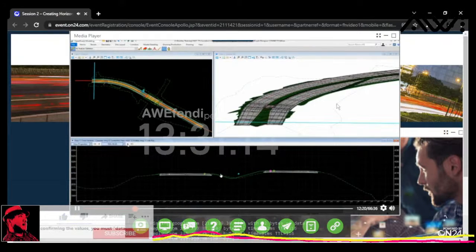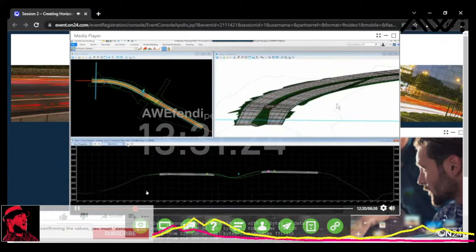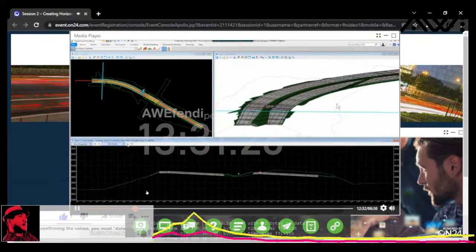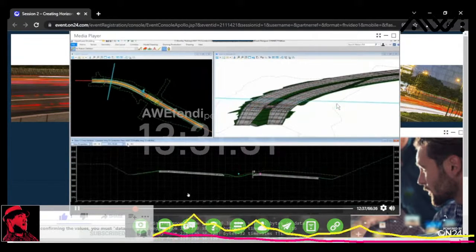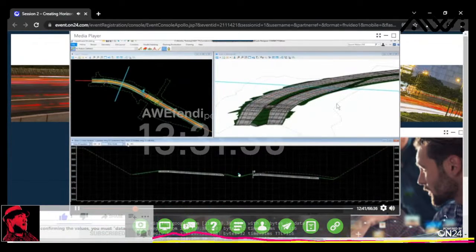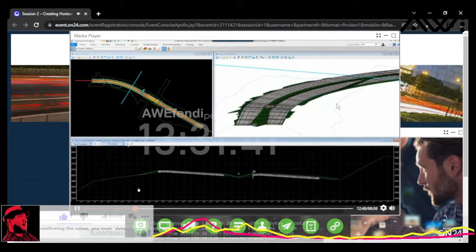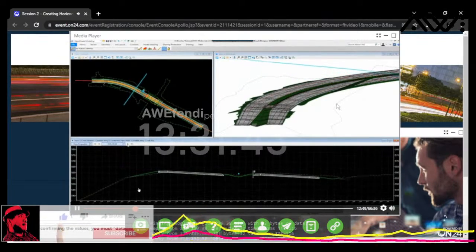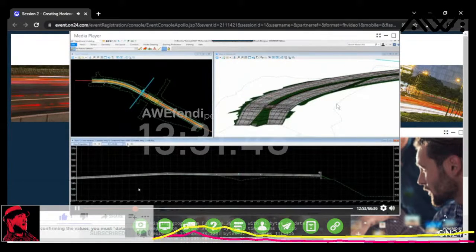We will modify, again, the eastbound lane, to meet existing both horizontally and vertically, and then we'll transition that back down to, again, our level or our even PGL. And as we walk through these sections, you can see now our elevations from westbound here and eastbound are equal at the same PGL. And so really that's our objective throughout the course of this project. Again, we're creating the geometric layout for that today. And so hopefully that gives you kind of a perspective of where we're going and why we're going to create the things that we're going to create today.